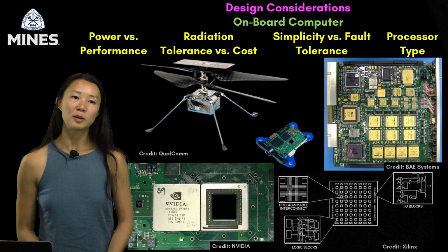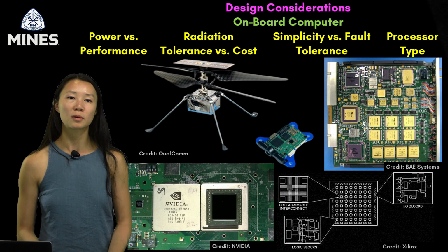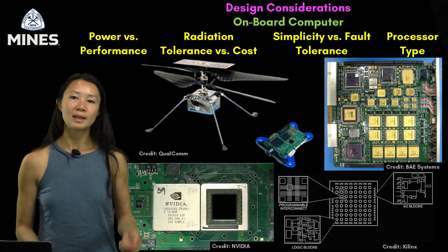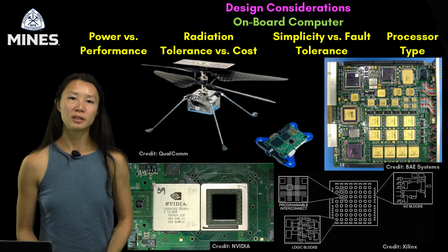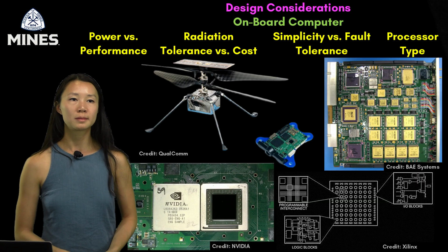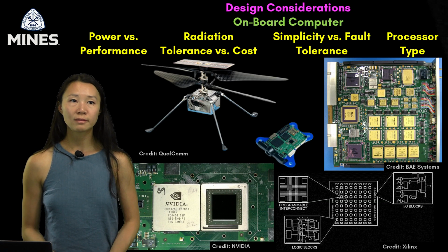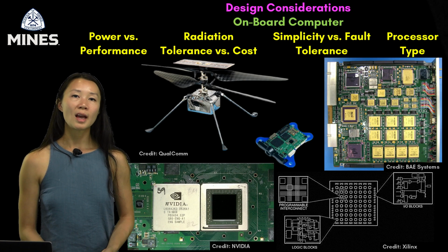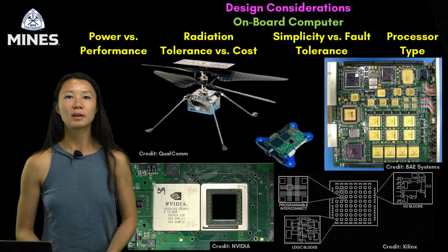They're especially valuable when low latency reconfigurability or rad-hard logic is required. You can think of FPGAs like muscle memory, where there's almost a reflex, whereas CPUs and GPUs have to go to some core processing. Depending on your mission, you should use a CPU when general purpose logic and flexibility are needed, a GPU when you're doing data-heavy or AI-driven tasks, likely for payload processors, and then an FPGA when you need custom, high-speed, or radiation-tolerant hardware control.